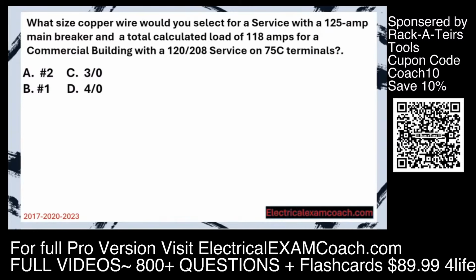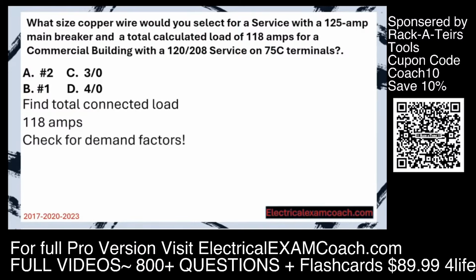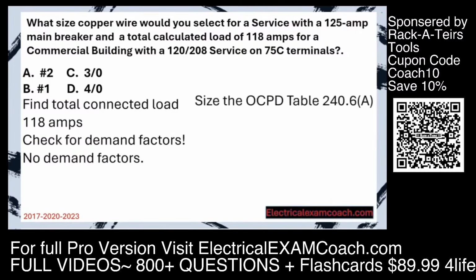Let's get to it. What size copper wire would you select for a service with a 125 amp main breaker and a total connected load of 118 amps on a commercial building with a 120/208 service on 75 degree C terminals? Step 1, we're going to find our total connected load. In this case, they give it to us. It's 118 amps, but we must check for demand factors. In this case, there are no demand factors, so we're going to carry on. Normally, we would size our overcurrent protective device, but if you notice in the question, they've already done that for us. So all we have to do is size our wire.